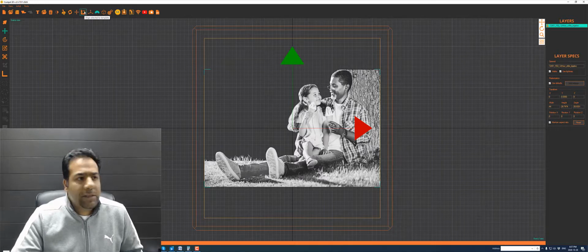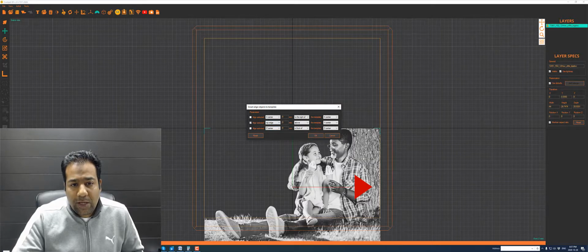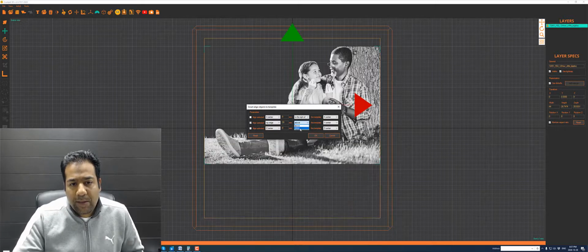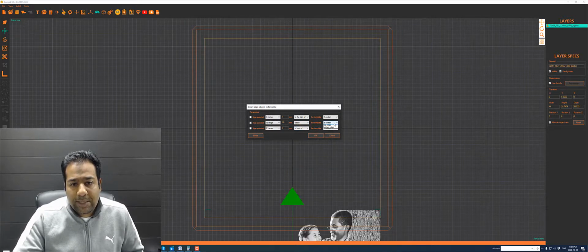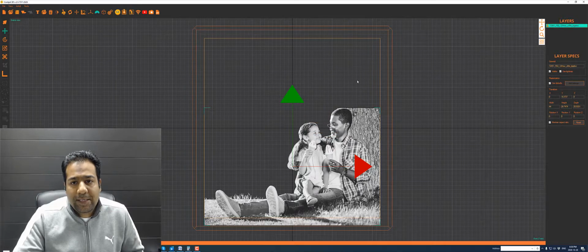There is a separate tutorial on this, but I'll just do this one quickly too. So let's just align. Let's say it's the top of this. I want to align the Y top edge, so the top edge of this, to be 20 millimeters, 2 centimeters, below the template's top edge. So align the top edge, which would be this edge here, to be below the template's top edge. So if I do this now, this here should be exactly 2 centimeters below this.